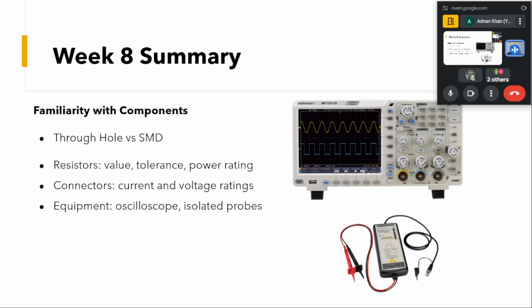Isolated probes have two terminals, where the positive will be connected to the positive terminal, and the other terminal will be connected to the ground, and these probes will be isolated. Let us say we want to see the switch voltages in the two legs of the top devices, the high side switches, which don't have the same ground.